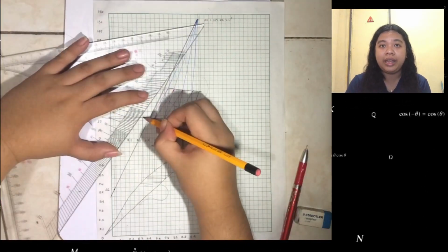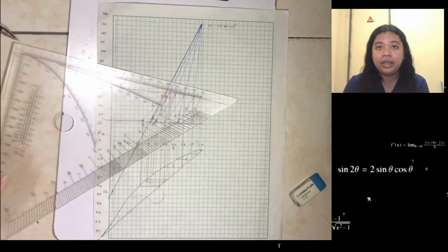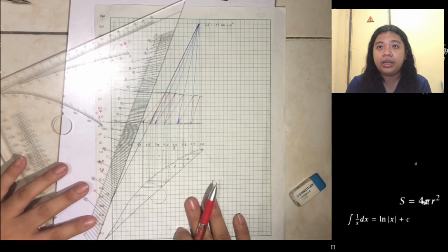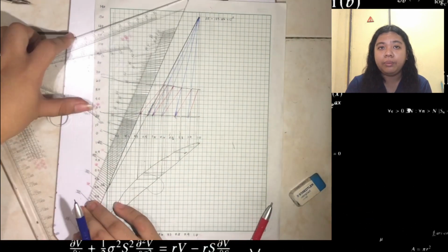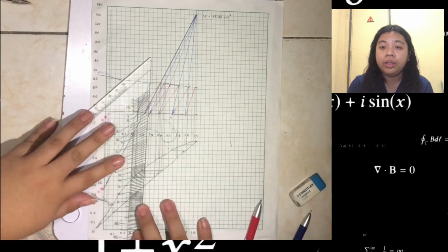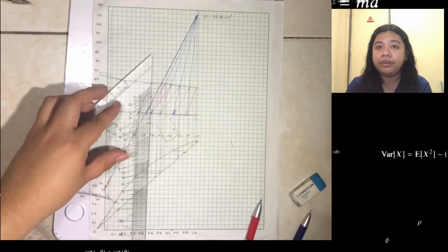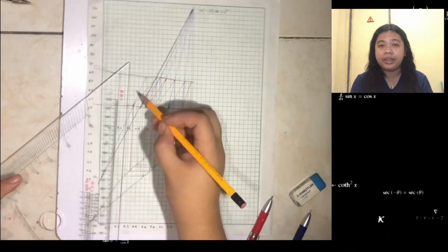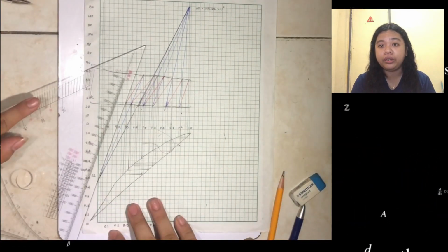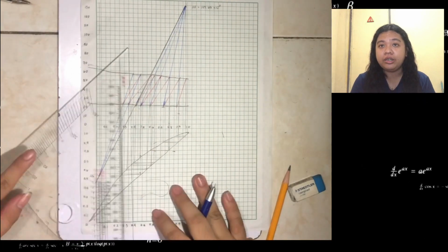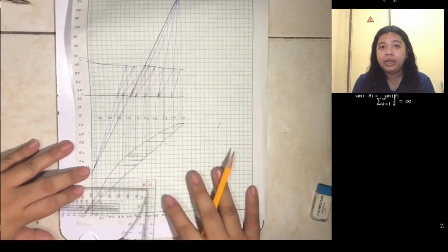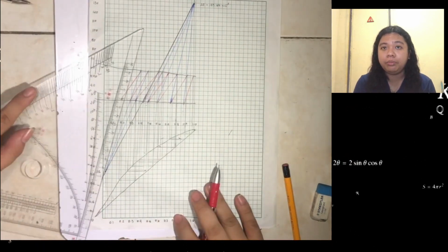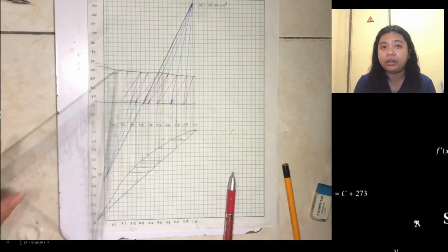Create an operating line from delta S, intersect it with the last HL point, and extend it to the HV and create the point. From the HV point, we create a vertical line to the 45-degree line and a horizontal line to the equilibrium and back to the HL line. Create a tie line from the HL point to the HV point by connecting them.